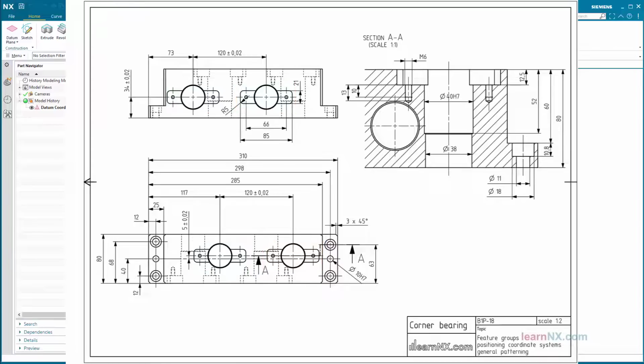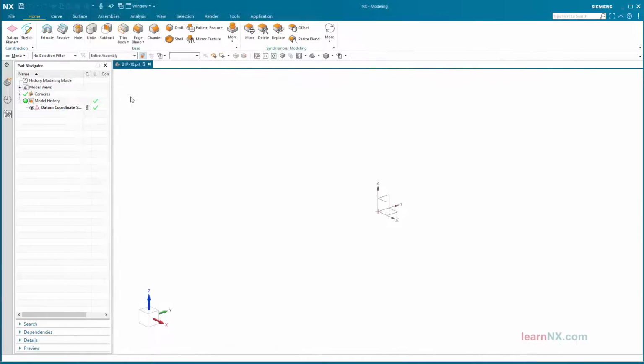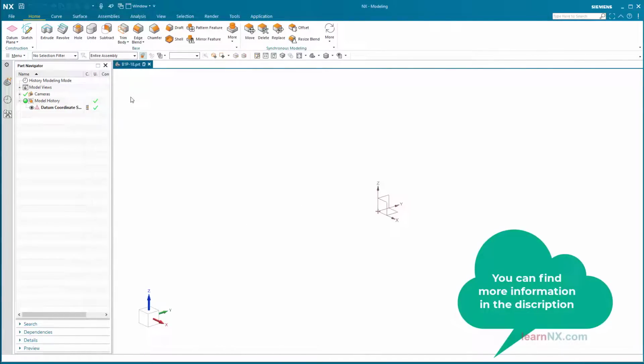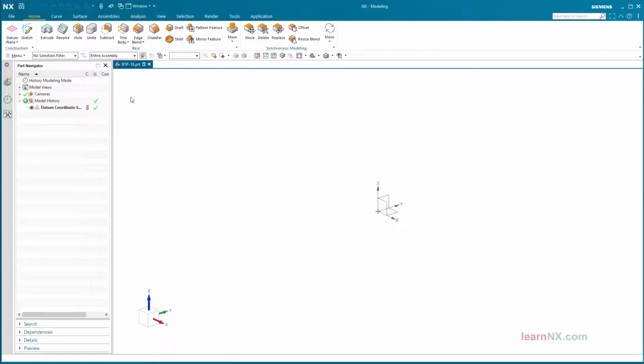For the sake of clarity, the base body and the receivings should be combined in feature groups. The customer defaults allow history-based feature groups, but also feature groups that can be freely moved in the history. Against the background of a uniform working method, but also in order to obtain data models that are as stable as possible, the following setting is recommended in the customer defaults.